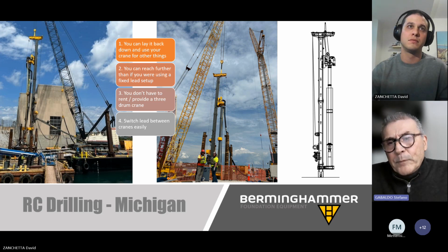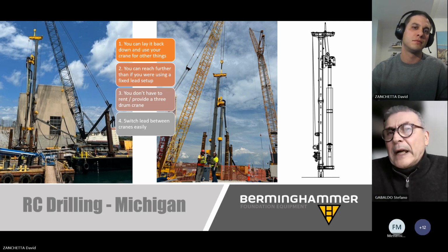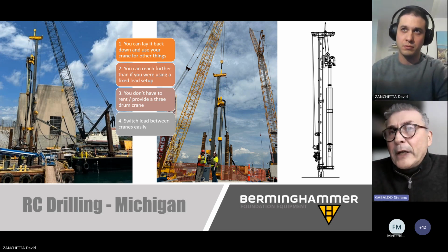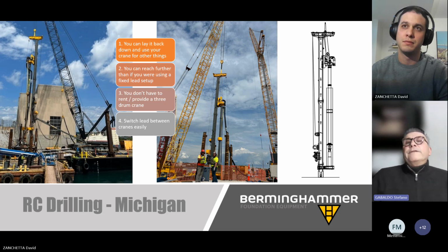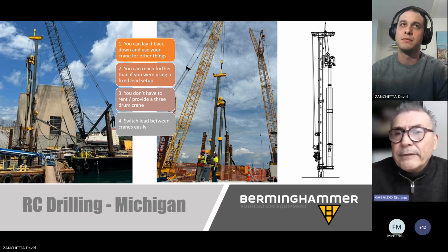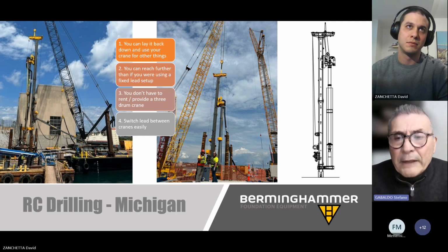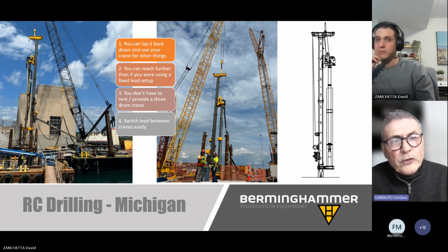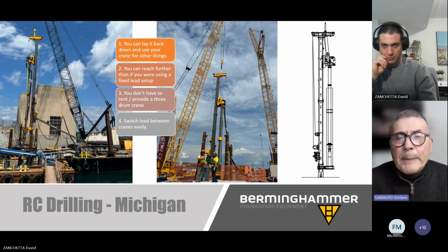Most of the time, our clients actually have lift cranes, in which case we either use an existing power pack from the client itself and mount it nearby, or we provide a support power pack bracket for the cranes so they move in unison, or we can supply the power pack if required. All of this typically goes through what we call a standalone valve unit. What this does is take the power out of a power pack and distribute it according to software and valves to the various circuits, whether it is a drill, a gate, a hydraulic clamp, or a winch.